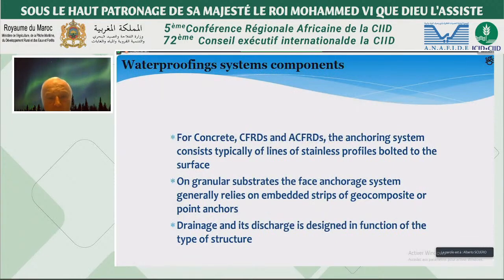For concrete face rock-filled dams and asphaltic face rock-filled dams, the anchoring system consists typically of lines of stainless steel profiles bolted to the surface. On granular substrates, the face anchoring system generally relies on embedded strips of geocomposite or point anchors. Drainage and discharge is designed in function of the type of structure.